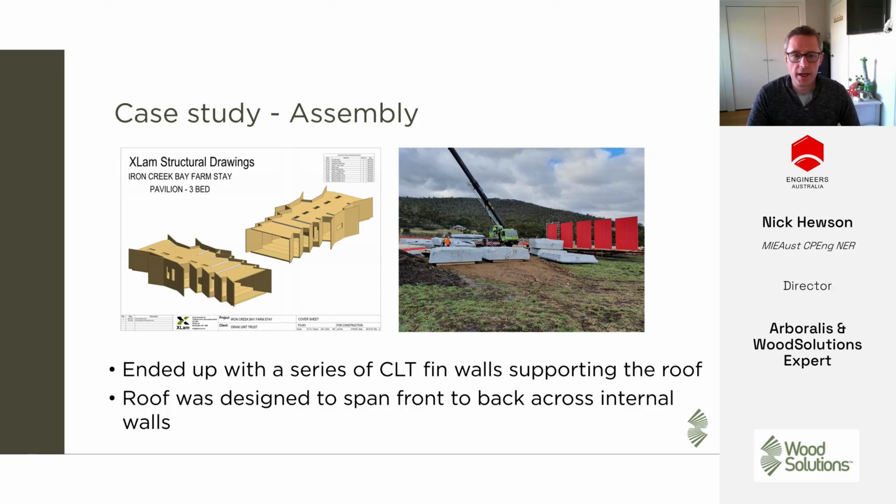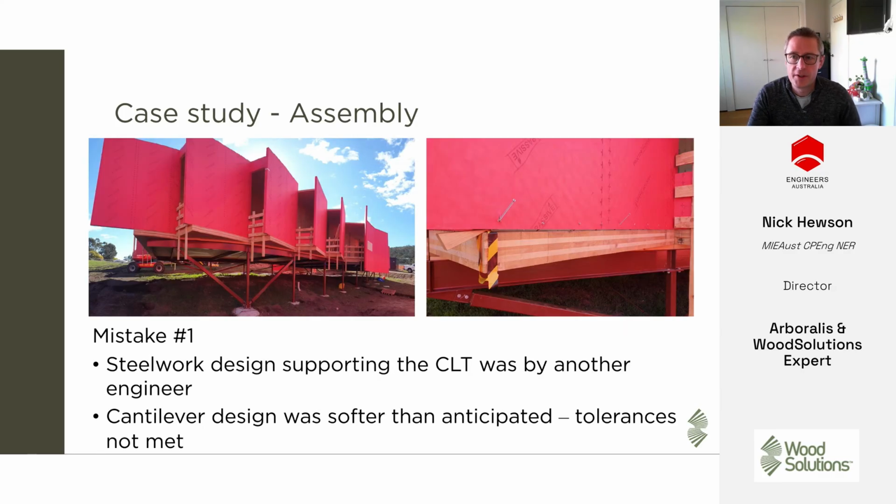But the actual design ended up being, call it, I don't know, a sort of armadillo creature with lots of windows looking out to the view, with a lot of thin walls. But yeah, certainly made some mistakes on this one. One was, there was a steel frame supporting all the structure, which was designed by another engineer, but because we didn't have the overall control of it, we ended up with a cantilever steel structure that was a lot softer than we anticipated.